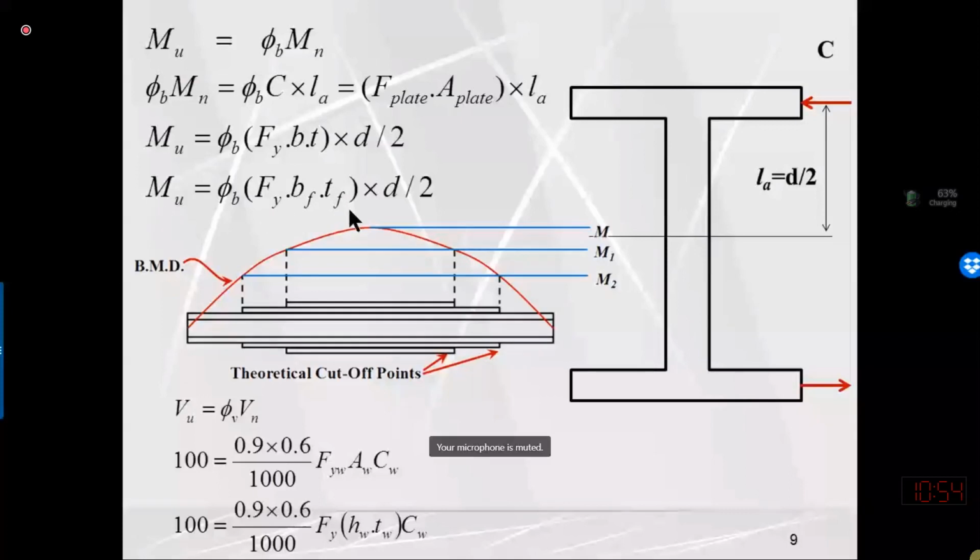In a hot rolled beam section, we are only selecting the beam section based upon the maximum bending moment, for example M, which is acting at the center. This maximum bending moment is produced only at a small portion. At another point, the applied bending moment is not M, rather M1. It means that if the moment is less at this point, we may require a lesser beam section, because if the applied bending moment is less, we can optimize it. So how can we optimize? There are three techniques.